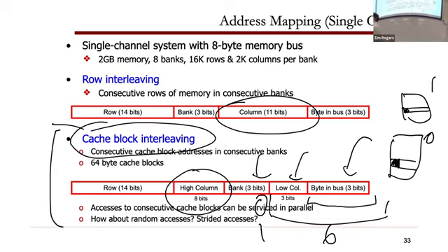And that's the mapping that you'll get. But logically now, my address space doesn't nicely fall across the row like it did in the first one. So your data is actually now sort of sprayed across different banks in that same chip from a logical address perspective. Does that make sense?